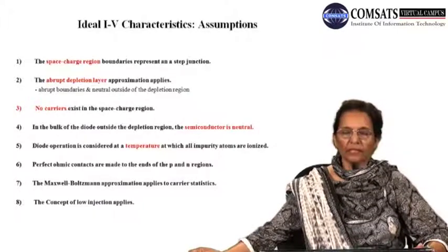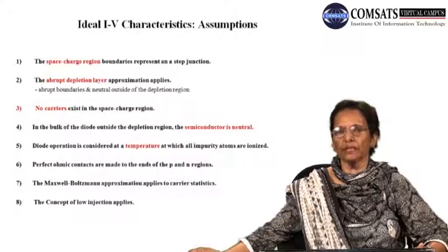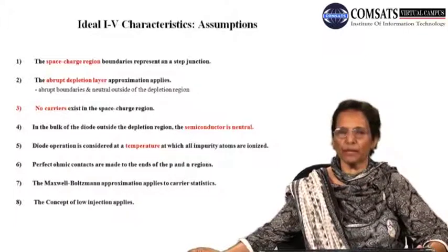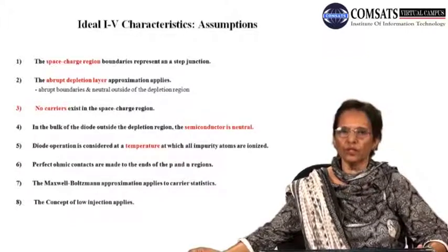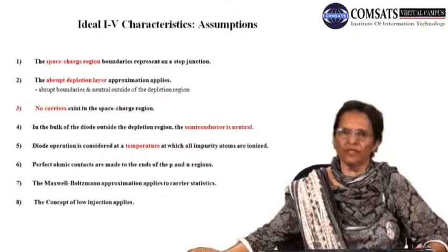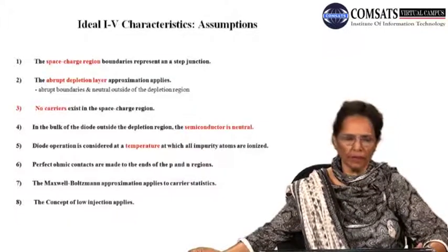What does this mean? This means that the dopant impurity concentration on the P side, which is acceptor atoms, suddenly reduces in concentration, and on the N side we only have donor concentration, positively charged donor ions, and if there is any acceptor concentration in the n-type region, it is almost negligible.